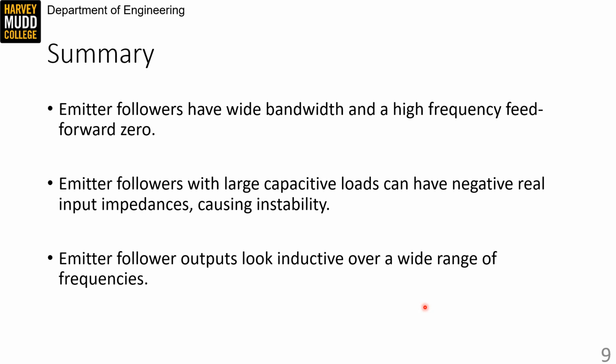So in summary, emitter followers have a wide bandwidth and a high frequency feed-forward zero from C pi. Emitter followers with large capacitive loads can have negative real input impedances, causing instability. And emitter follower outputs look inductive over a wide range of frequencies.